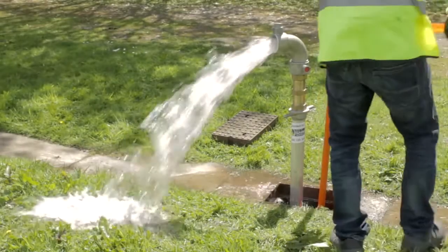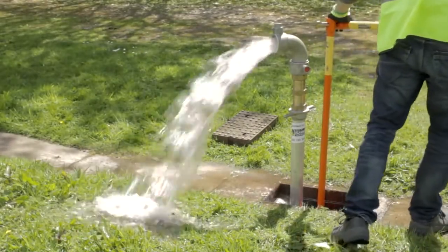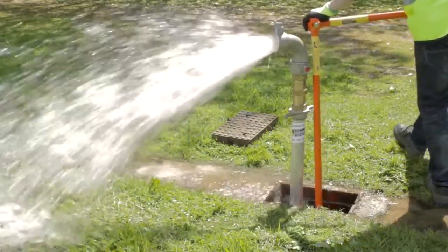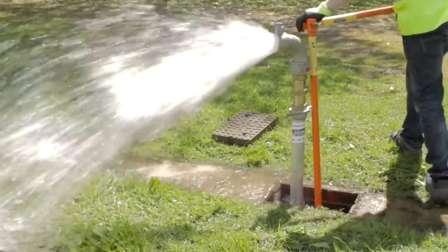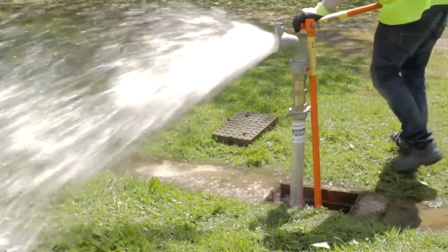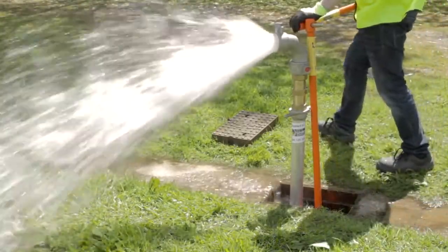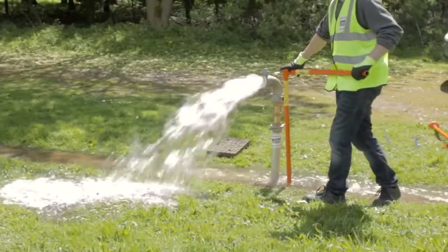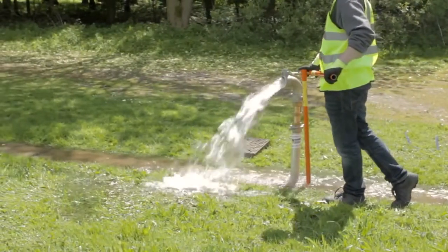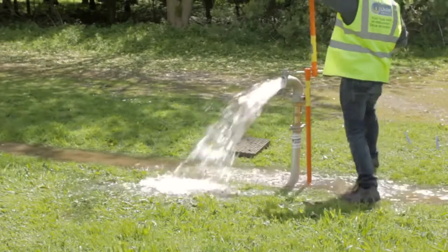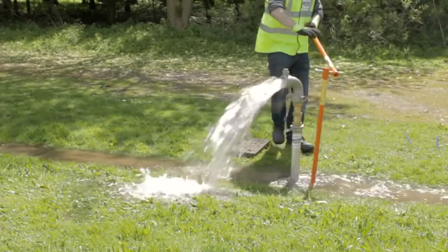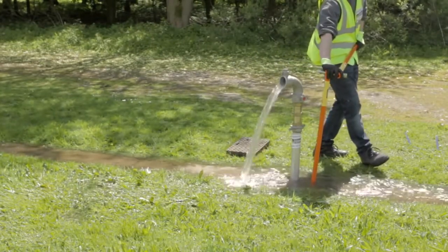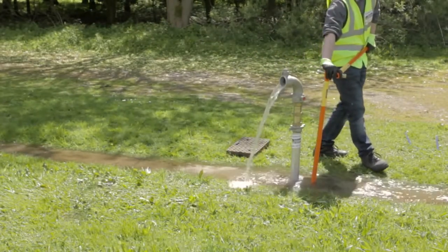In certain circumstances, you may be allowed to use a large diameter standpipe. This shows use of a standpipe in common use with the fire and rescue services. Remember, the larger the standpipe, the more critical is the speed of operation. It is worth noting that in an emergency situation, operating hydrants too quickly could cause bursts and potentially restrict your availability to extract the amount of water you need.